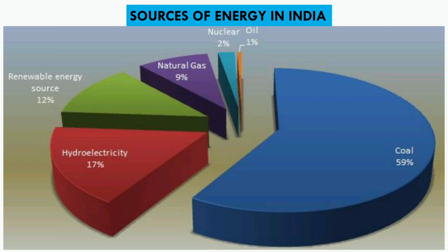Gujarat and Rajasthan are deficient in both water and coal resources, and therefore nuclear power should be the main source of power generation. However, in Gujarat, the small water potential and natural gas available can be utilized to meet the peak loads. The installed capacity of the steam, hydro, and nuclear power stations in Gujarat is 4,010 megawatt, 420 megawatt, and 470 megawatt respectively.